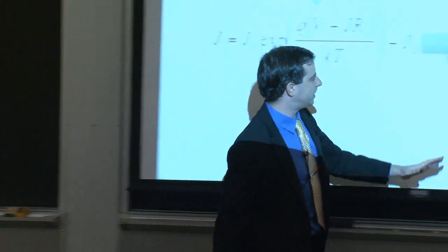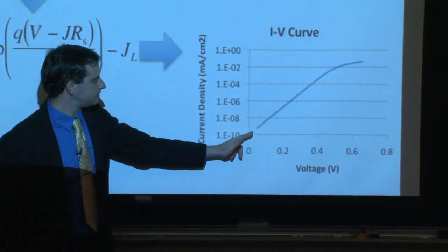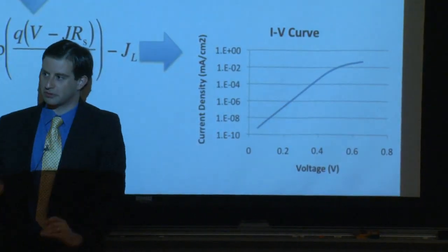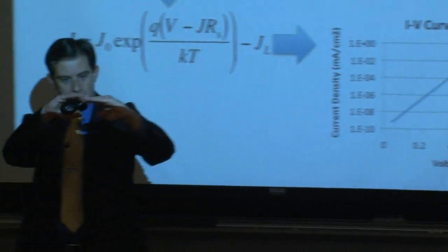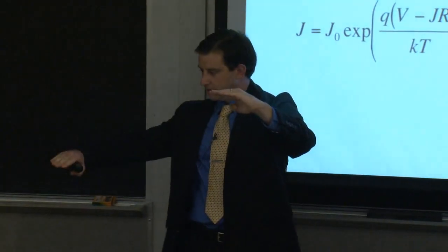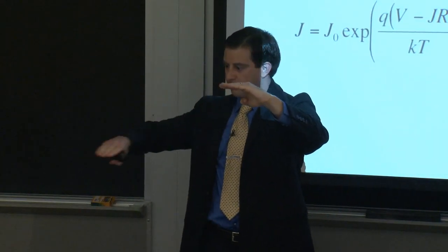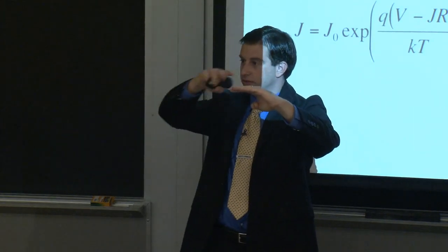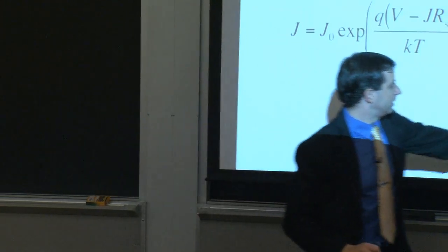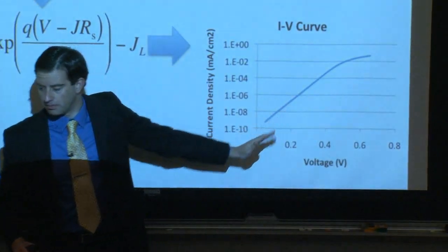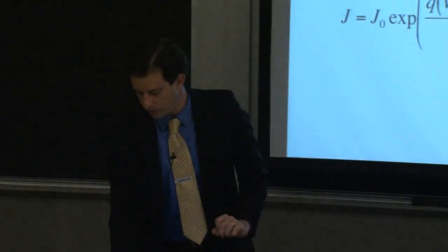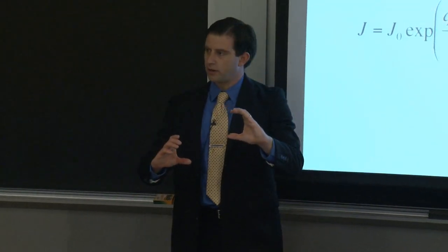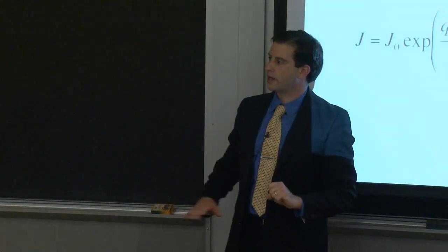So think of this as being a very strong diode. In the absence of shunt resistance, you have a very strong diode. You have in your p-type region, in your n-type region, that large barrier preventing the diffusion of electrons back into the device. It's preventing this from rising. It's keeping it low. And that can only happen when the p-n junction barrier is uniform throughout your entire device.